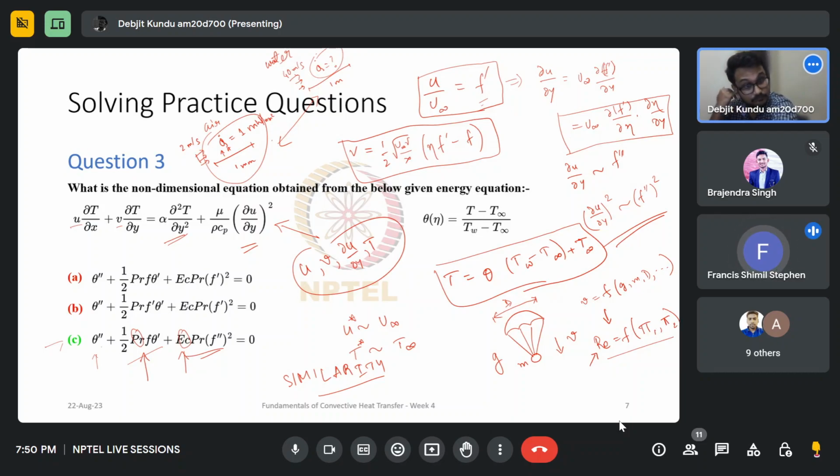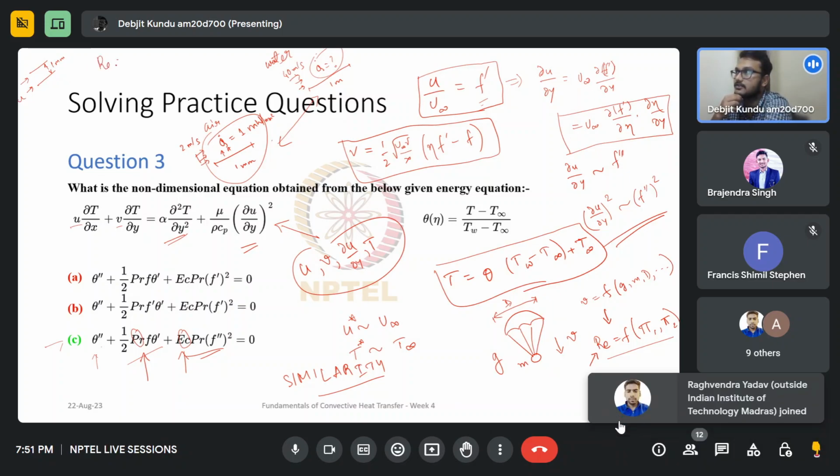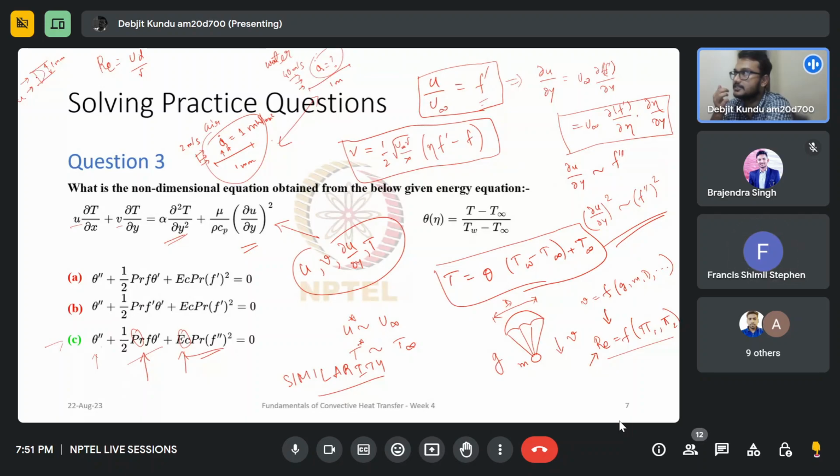So like if we are using the Reynolds number, it's actually rho VD by mu, isn't it? So for both cases, the diameter will be different, isn't it? So yeah, we will be having two different values of Reynolds number. Yeah, correct. This is a very good example. So let's say I have a pipe like this, which is of 1 millimeter, and I have some flow through it, let's say U, and ultimately I can use this Reynolds number equal to UD by nu, right? So I get some velocity from this.